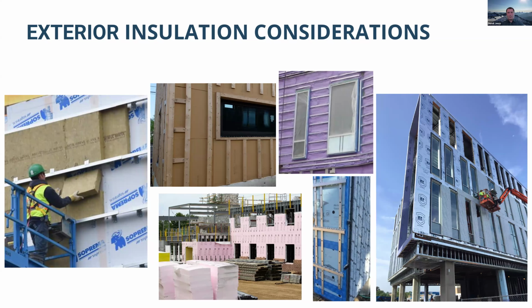We do need to talk about air barriers as well. This is another critical part of the enclosure. This is often actually one and the same as the WRB. Quite often these membranes will be serving multiple purposes. A lot of them are a water-resistant barrier and an air barrier. They're designed to do both, so they will stop airflow and water. Some of them will also be vapor barriers, so they will stop three different things: vapor diffusion, airflow, and water.